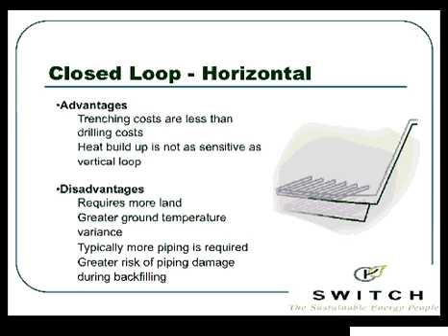How deep do you have to dig? It's really dependent, Ben, on what ability you have. Typical boreholes are 200, 300 feet deep, because we're going to need 200, 300 feet per ton of air conditioning equipment. On a typical house we have a 3-ton system, or for bigger houses nowadays, 4-ton and 5-ton systems. You'll see in a later slide that you need 5 or 6 boreholes at 200 feet deep, and you'll see in the slide as well how much trenching you need.